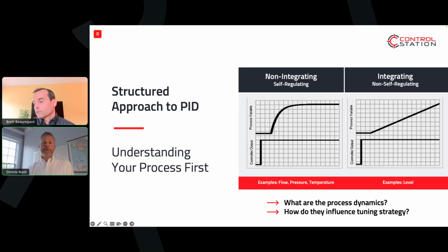Sarah, let's advance. Sure. Great. So when we think about modeling and tuning with the objective of consistency, with the objective of efficiency, we like to start with understanding the process itself. As represented on the screen in this slide, a simple place to start is whether or not you have an integrating or a non-integrating process. That will influence the approach that you take, whether from the perspective of the bump test, the type of bump test, the size of the bump test, other attributes within your process, the noise level, interaction, etc., that will influence the dynamics of the process. All of those components will have a direct impact on the approach that's applied.